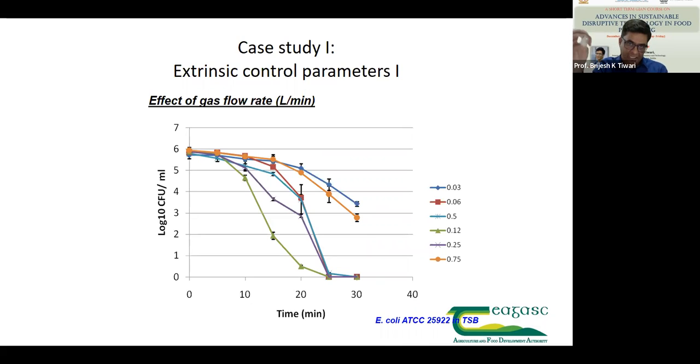Whereas when bubble size is very small, there is an excessive amount of ozone, but channelization is possible, that is, channel formation. That means all the bubbles form a stream and just escape the bubble column reactor. Whereas when we have an optimum bubble size, which can cause agitation in the liquid, that makes a completely different application.